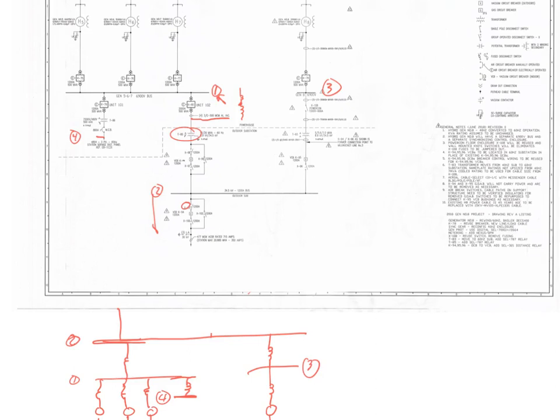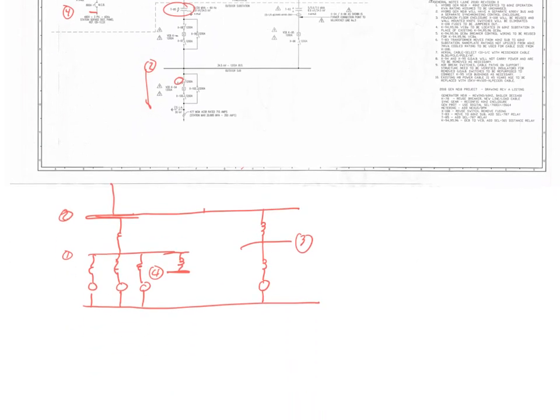Questions on the positive or negative sequence? The only difference between positive and negative sequence, at least for our purposes, is these sources. In negative sequence land, those are removed. So all these admittances are X1s. So X1 of that generator, X1 of the next generator. Transformers tend to always have the same impedance, so these are always the X1s, right?